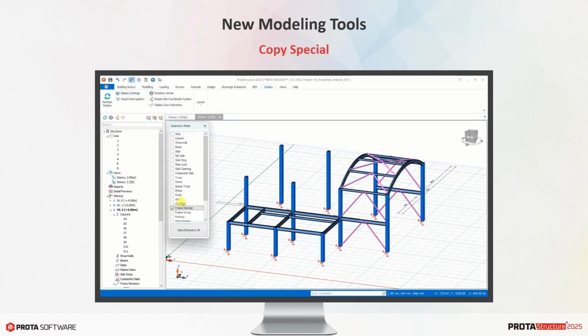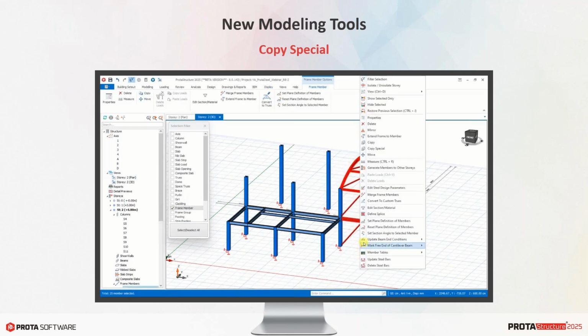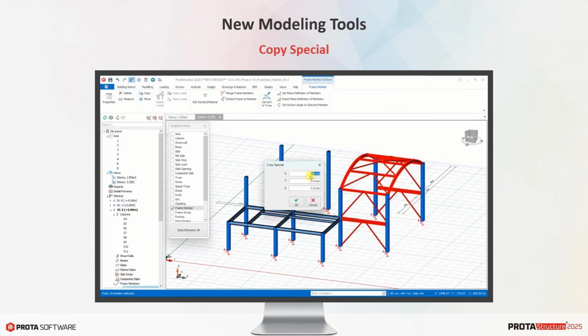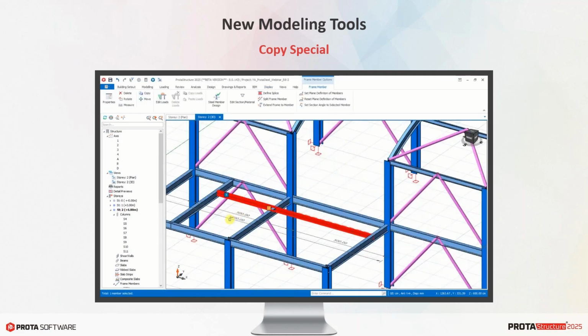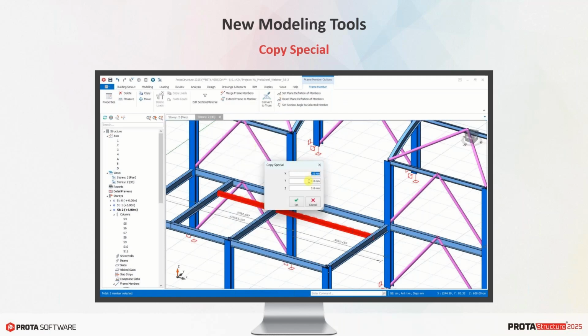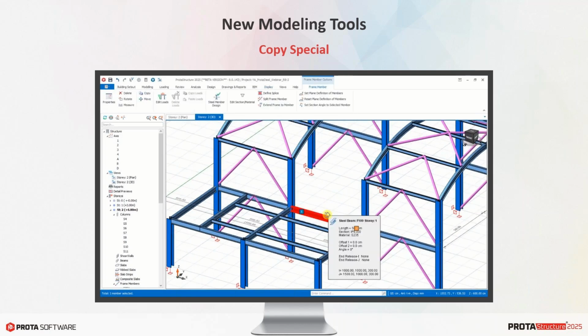During modeling, sometimes you need a member to be copied to an exact distance, but you cannot find a snapping point to hold on to. The Copy Special command helps you copy your member with given offset distances in global X, Y, and Z directions. You can also provide a repetition count so that the selected member gets copied multiple times by the given offset values. With the following minor updates, again, we will provide the Move Special command as well. You will be able to move axis-independent members freely, just like the Copy Special command here.